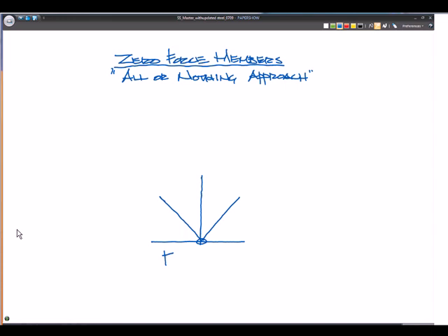Okay, and at joint F, we have a 6-kip point load hanging off the bottom of this. So if we did sum of the verticals equal to 0, we have 6 kips going down and we need 6 kips going up.